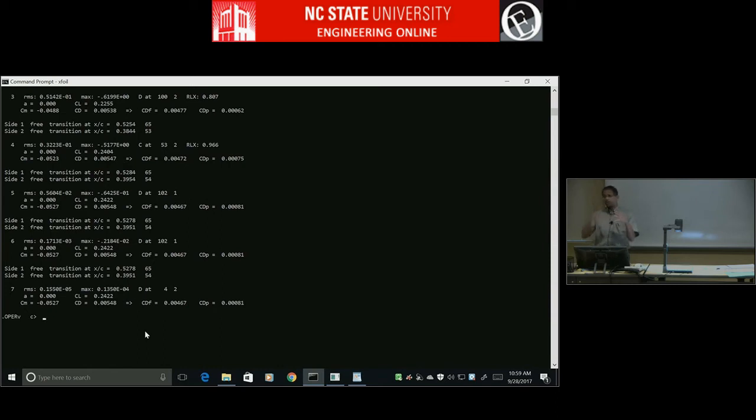It's doing panel method, boundary layer, and looping that. When you ask it to do a particular CL, on top of that, it'll also iterate on alpha. So sometimes, especially if you're trying to make it do a lift coefficient near stall, it's varying a lot of things and the numerical method won't converge properly. So it's better to just run alphas in viscous mode.